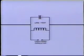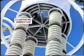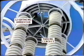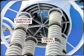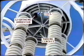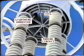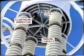It is essential that the line trap be protected by a lightning arrestor, as the main inductor coil could become seriously damaged by lightning surges. The lightning arrestor is often placed inside the wave trap along with the tuning hardware. During faults, the large inductor is subjected to very strong mechanical forces which tend to force the coil apart. This may damage the end connections.